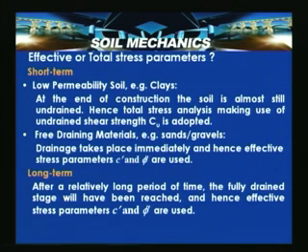So, for effective or total stress parameters: in the short term, for low permeability soil, for example clays, at the end of construction the soil is almost still undrained, hence total stress analysis making use of the undrained shear strength is used. For free draining materials like sands and gravels, drainage takes place immediately, hence the effective stress parameters C dash and phi dash are used. In the long term, after a relatively long period of time, the fully drained stage would have been reached, hence the effective stress parameters C dash and phi dash are used. So, based on this judgment, one can perform either effective stress analysis or total stress analysis for the stability of a particular slope under consideration.